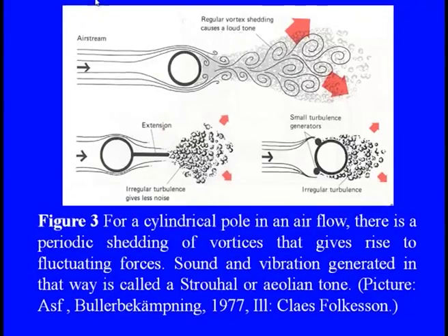So, even in these cases, whatever vibration or sound is generated is, as we already said, the Strouhal or Aeolian tones, and we need to check what exactly the shedding effect is, which can be related straightaway to the dipole feature.